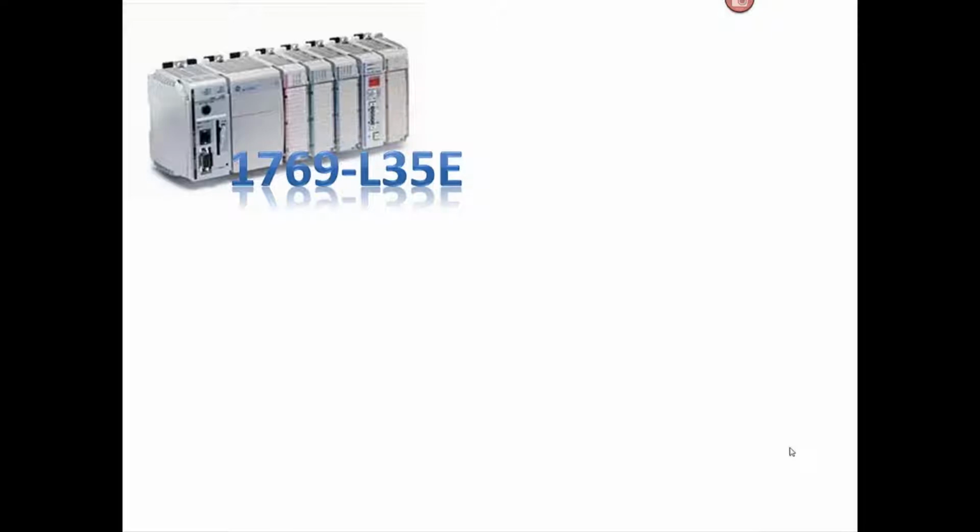Starting from the left, you have an end cap, then the processor, then a 1769 power supply, 3 I/O modules, a DeviceNet scanner, and another I/O module. Not exactly the hardware configuration we're going to use. It's just a picture I grabbed off the web. But we're going to have an L35E, as you see, a power supply, and then a digital output module, a digital input module, and a combination analog input-output module. So we only have 3 I/O cards.